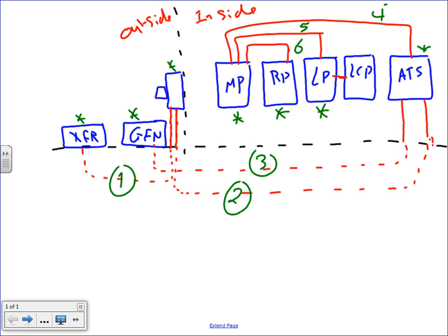These are the numbers of the feeders, because ultimately you need to have a feeder schedule. So I start numbering them from the transformer. The transformer coming into the meter, the CT cabinet, is number 1. Out of the CT cabinet into the auto transfer switch from the transformer is number 2. The gen is number 3. Out of the auto transfer switch to the main panel is number 4. And 5 into the lighting panel, 6 into the receptacle, and that one here is 7.